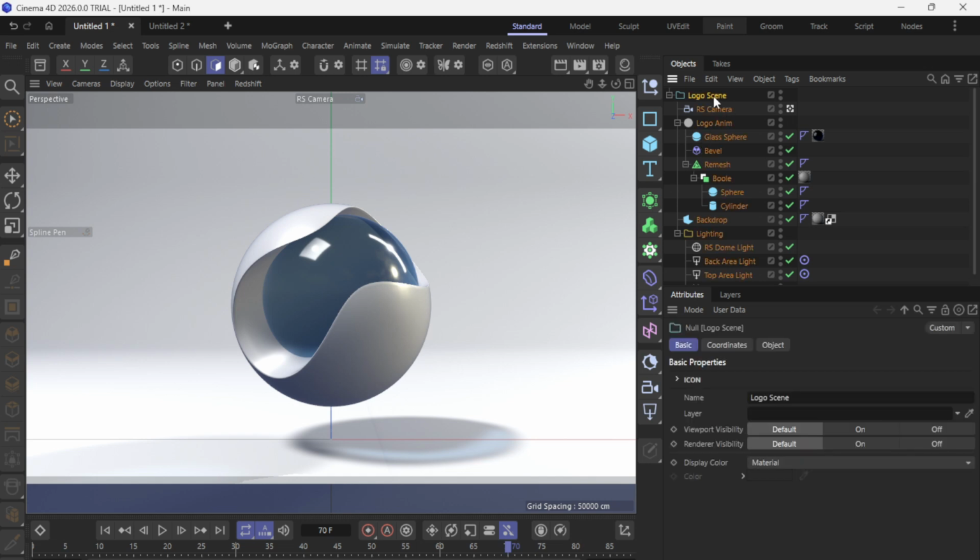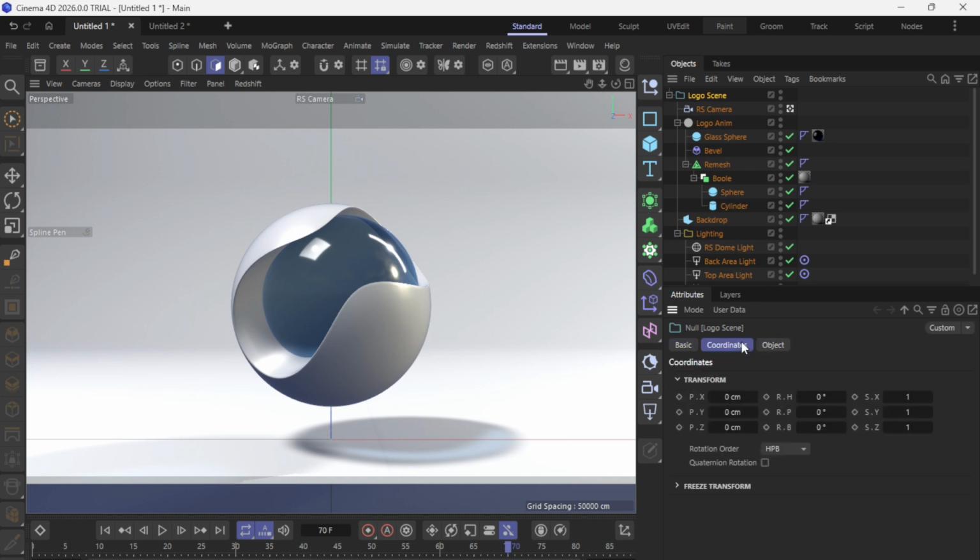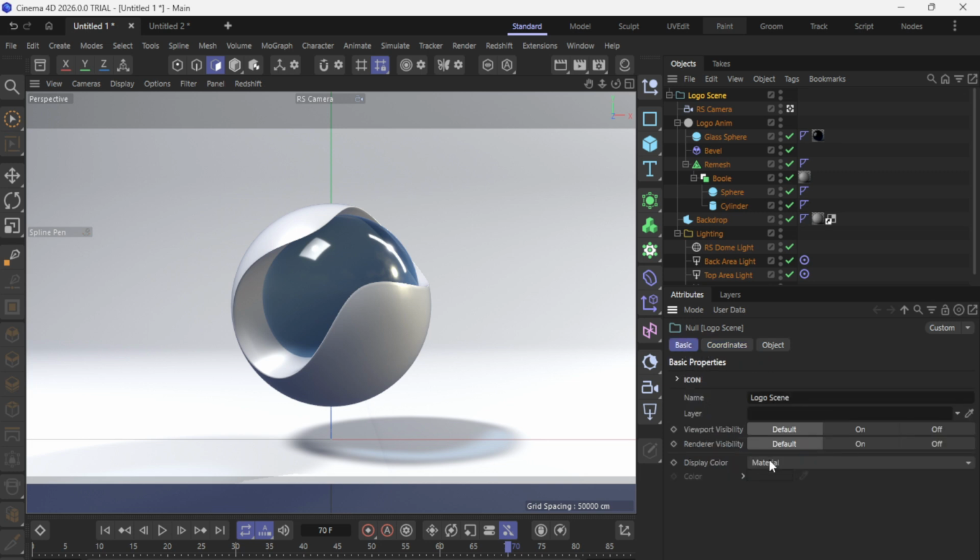If your Illustrator document was designed in millimeters or inches, choose a scale that makes sense for your Cinema 4D project units so the artwork doesn't arrive too tiny or gigantic. Don't worry if you're not sure, you can always rescale the splines later.